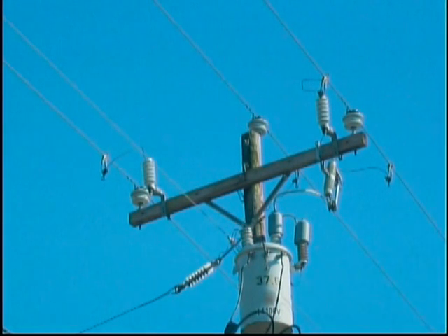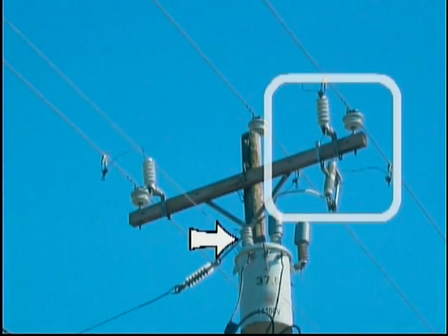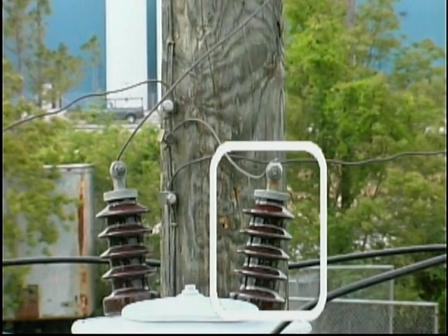Here is an example of a two bushing transformer connected to a Y primary system. In this example, the transformer is rated for the phase to neutral voltage of the Y system. The H1 bushing of the unit is connected through protective devices to a primary phase wire. The H2 bushing is connected to the grounded system neutral.